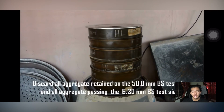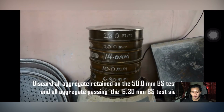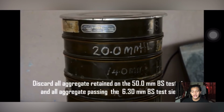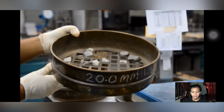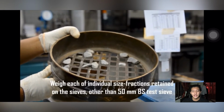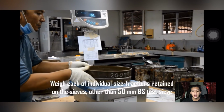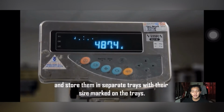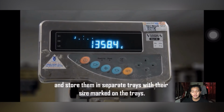Discard all aggregate retained on the 50.0 mm BS test sieve and all aggregate passing the 6.30 mm BS test sieve. Weigh each individually sized fraction retained on the test sieve other than 50 mm BS test sieve and store them in separate tray with their size marked on the tray.